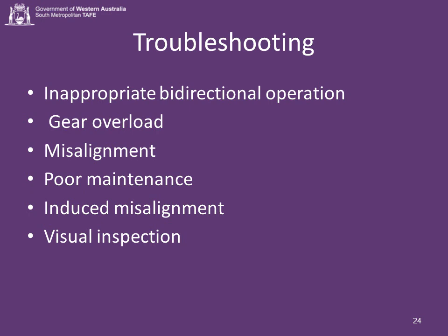One of the primary causes of gear failure is the fact that, with few exceptions, gear sets are designed for operation in one direction only. Failure is often caused by inappropriate bidirectional operation of the gearbox or backward installation of a gear set. Unless specifically manufactured for bidirectional operation, the non-power side of a gear tooth is not finished. Therefore, this side is rougher and does not provide the same tolerance as the finished power side.